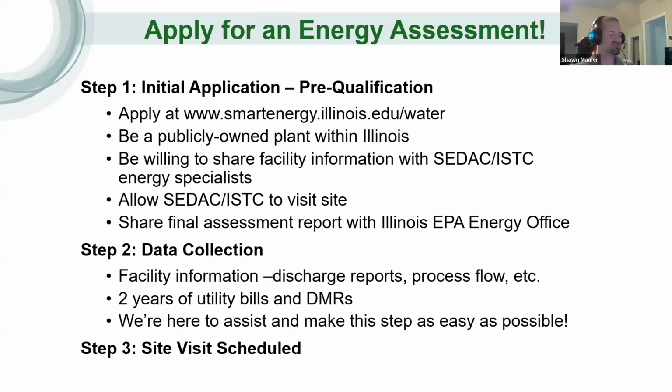The site visit is usually about a 2 hour to 3 hour assessment, depending on the size and complexity of your facility. We'll walk through, document the different process components, the condition of equipment, mainly gathering nameplate information off motor nameplates, things like that, to help us with documenting energy consumption, breaking out that energy into buckets of use, such as aeration, treatment, filtration, things like that. So that helps us target where to do energy efficiency improvements.